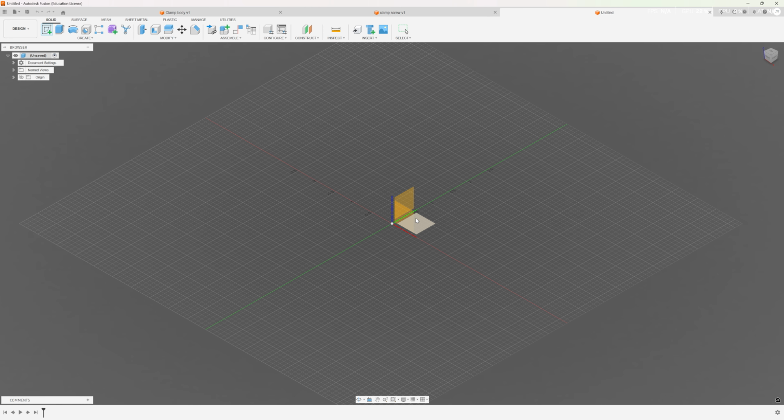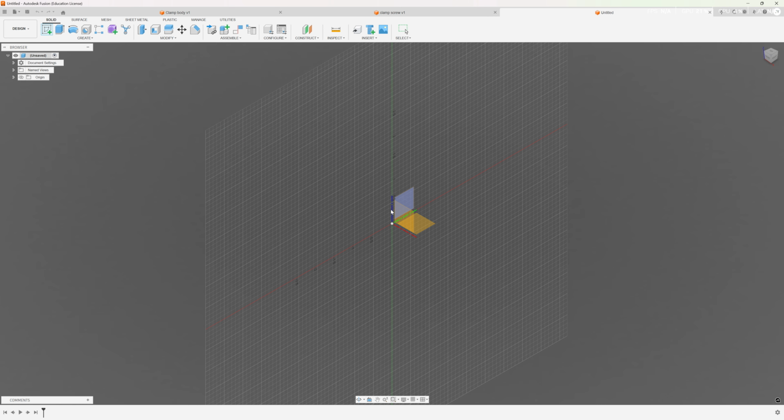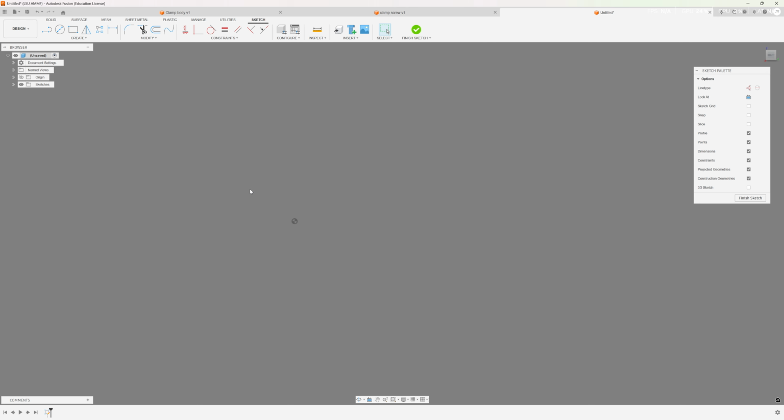So I'm going to do create sketch, and I'm going to go in my ZY plane because I know I'm going to do a revolve like I was talking about previously, because this is going to be a little more complex of a geometry where the revolve function is going to really show its worth. So I'm going to come up, over, whoops, escape, line, and finish it out.